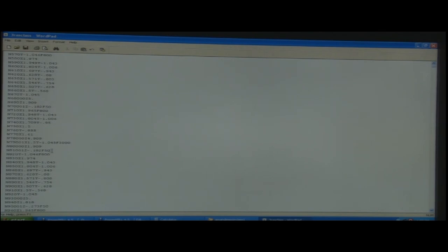Now, once it has plunged in, the next command makes the feed 800 that was set there. This is cutting mode. The cutting feed is 800 millimeters per minute. So, this is plunging feed, cutting feed and rapid feed. These are the movements of the tool. These are three different feeds, and this is the whole code that is written here.